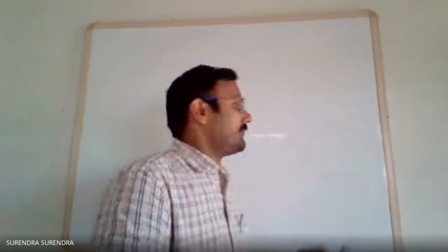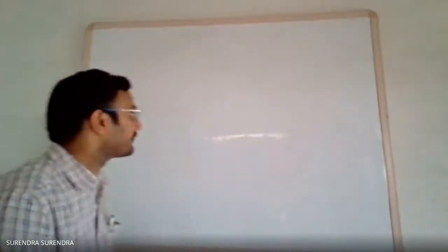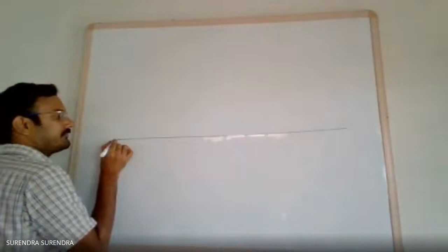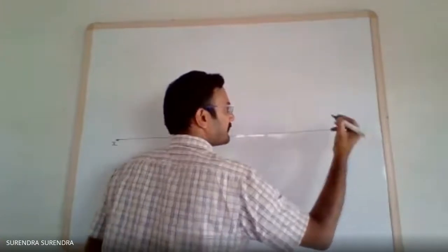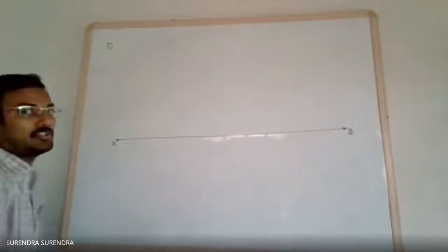Above or in front of, as in most of the cases we discussed, the default is first angle projection, assuming the object is in the first quadrant. This means always drawing the front view above the XY line and the top view below the XY line. So first, draw the XY line. Name the problem number 1 on the top right-hand corner.